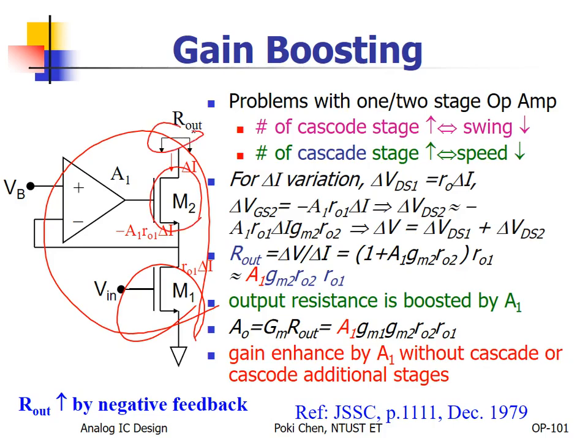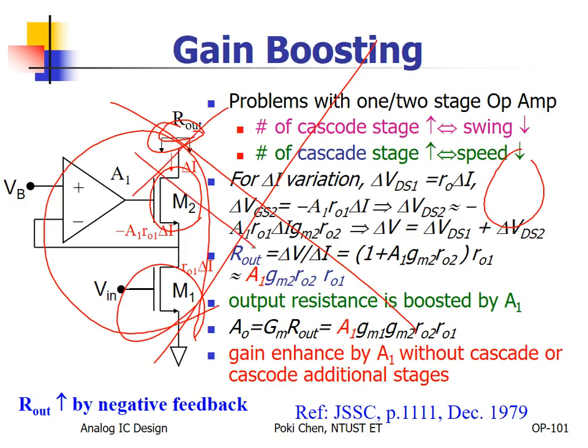But don't apply another cascode. If you apply the second cascode, double cascode, sorry for that, I promise you, 0 volt for your operation range. It cannot work, it cannot be functional, I mean for the best performance. It means the gain will be decreased. Then you simply waste your effort, your chip area, your money, right? So usually, even though it is possible for MOSFET, we don't apply any kind of double cascoding. If single cascode is no good, then we can use such kind of gain boosting.